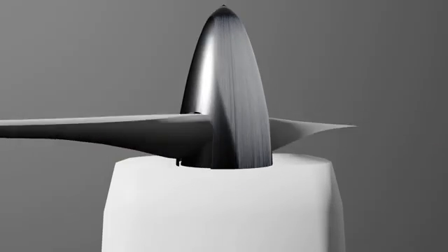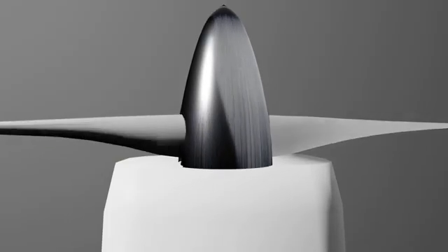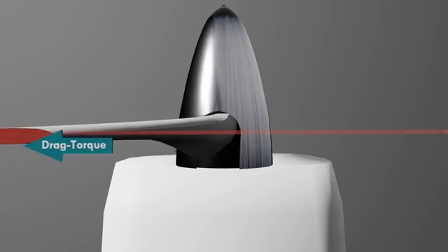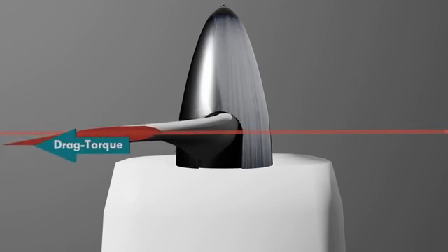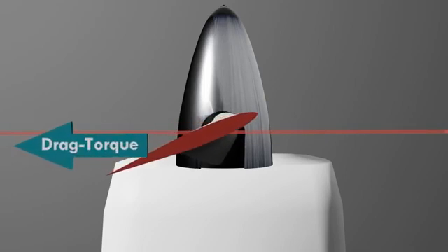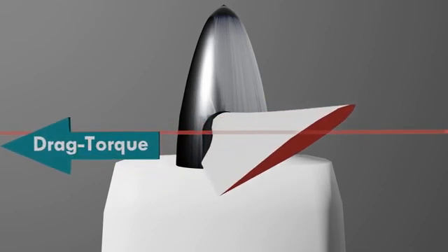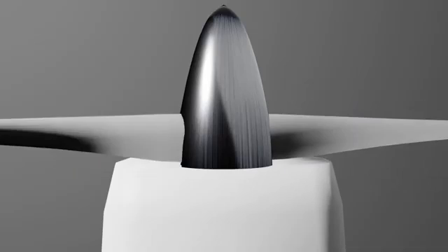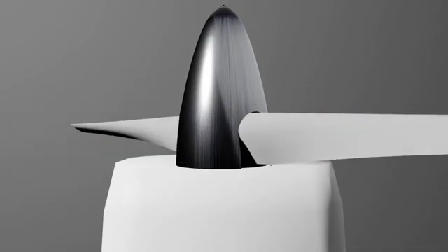For example, if the throttle is opened, the engine will produce more torque. How should the governor react? By increasing pitch to what's known as a coarse pitch. Induced drag increases, and this balances out with the increased engine torque from earlier to maintain that RPM.